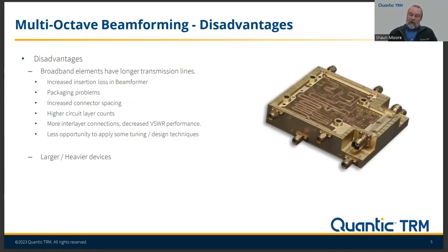The first is that most of these devices require a multi-stage transformer or distributed network. As soon as we go into multi-stage or cascaded networks, you have higher line losses because of copper. The circuit is going through a longer path, therefore it's going to have increased insertion loss.